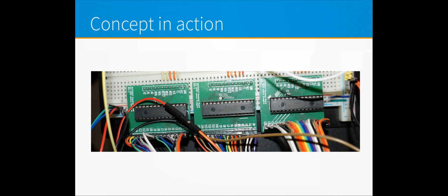And I don't remember the order I put these in, but generally 2 of these will be, well, no, they will be your address lines, and this one would be your data line. And underneath here, these lines that say A0, A1, and A2 are what you do to bias the address. So this one would be 000, 100, 010. So they all have unique IDs, and you can actually tell the command you send which one you want to send it to by including this ID.